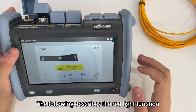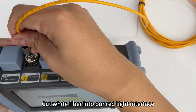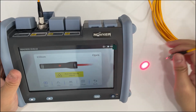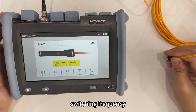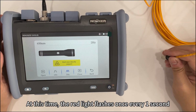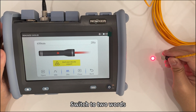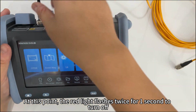The following describes the red light function. Plug the fiber into our red light interface. After opening it, you can see normal red light emission. Switching frequency. At this time, the red light flashes once every 1 second. Switch to 2 Hz. At this point, the red light flashes twice in 1 second then turns off.